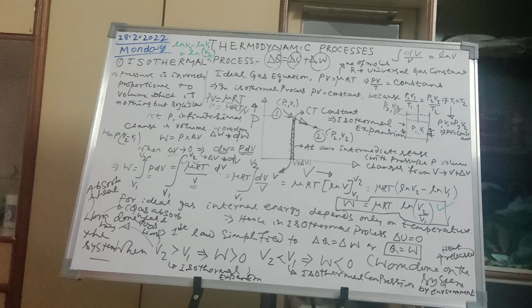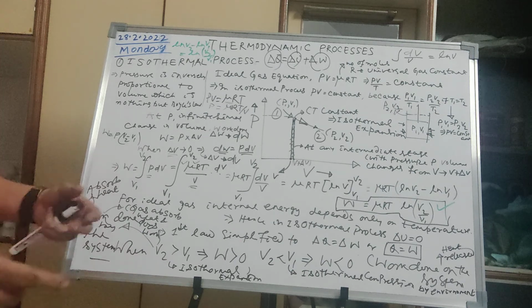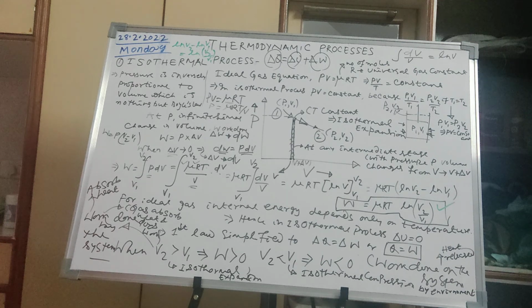There is suction, compression, power, and exhaust. In any internal combustion engine, like a petrol engine or diesel engine, these four processes happen. In a four-stroke engine, the fuel efficiency is better because all four processes take four strokes, whereas in a two-stroke engine, all these four processes complete in only two strokes. Two-stroke does not have better, complete combustion, so efficiency is less. So it is very important to know the efficiency. So what does efficiency mean?